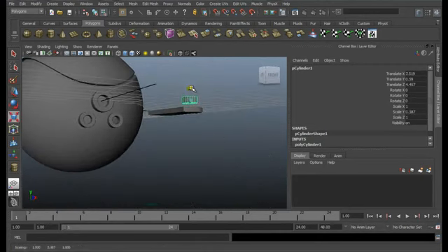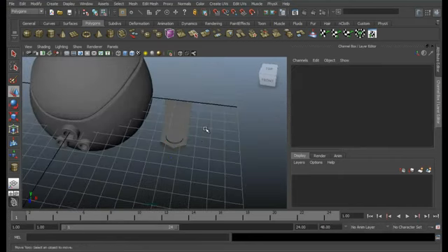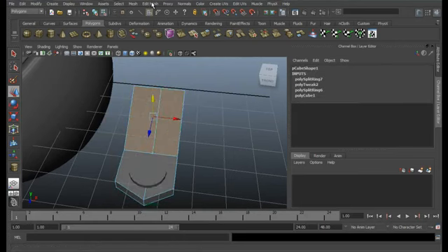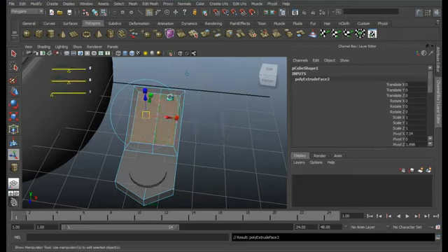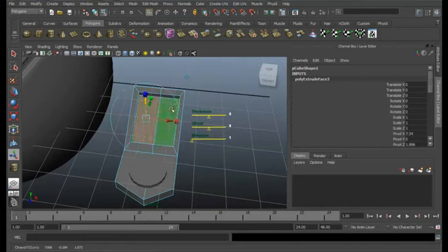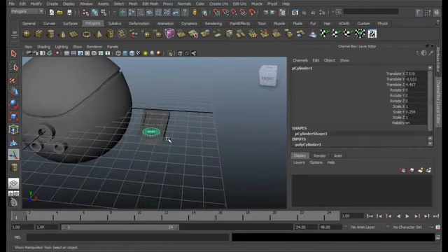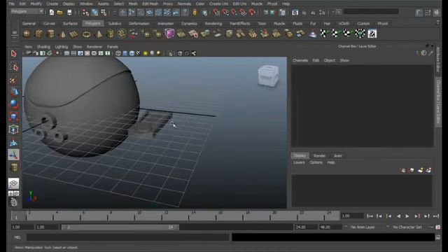Decrease the height. Like this. Go ahead, select two faces, edit mesh, extrude, and just decrease the size. This one. Then again press G key to use extrude once again, and just press it inward. I think that's it. This much will do. Let us combine these two. Combine. Okay, it's done.